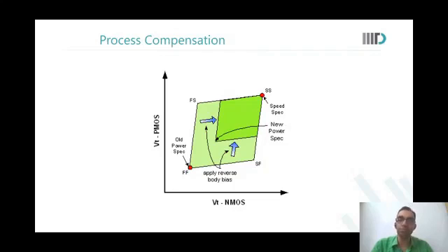But the devices are fast, so you say, and my leakage is very high. You say, oh, can I do something to arrive at 2 gigahertz instead of 3 gigahertz? But I reduce the leakage. So what would you do? You can do multiple things. You can, for example, apply body bias.